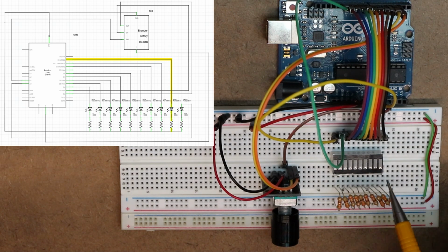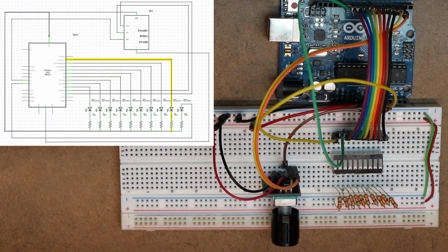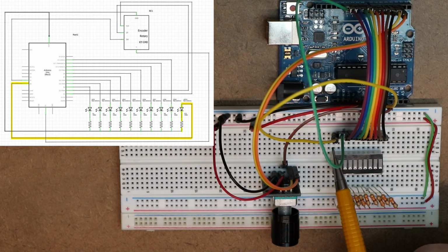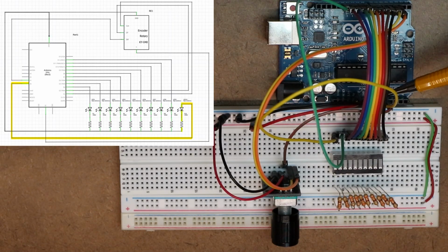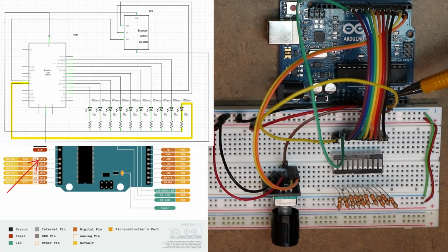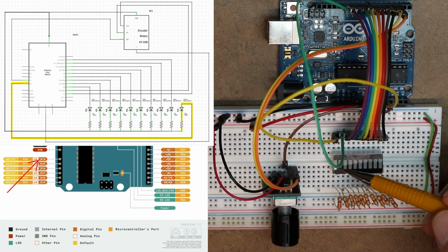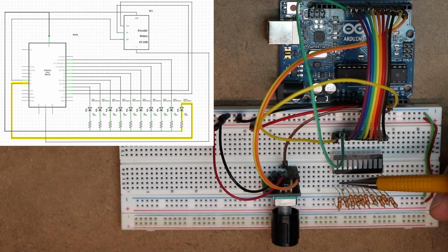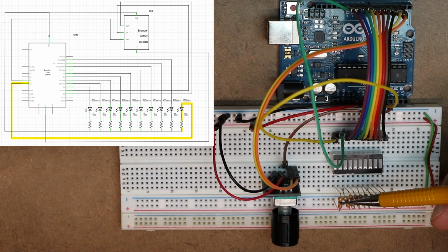Now I don't really like to use pin 13 on the Arduino if I can help it, because anytime pin 13 goes high, so does this LED on the board. So I just kind of stay away from that. If I've got other pins, I'll use those first. So in this case, we're going to use a pin going to A0, or digital pin 14. That's going to power our LED going to the anode, and then again coming out the negative side of our LED, or cathode side, to the resistor and to the power rail.